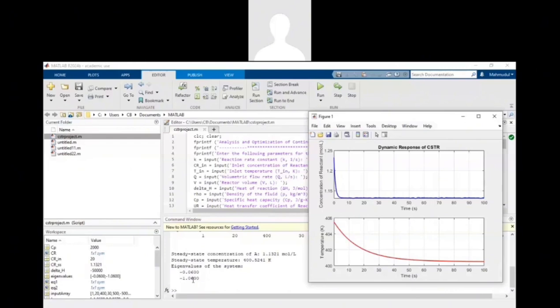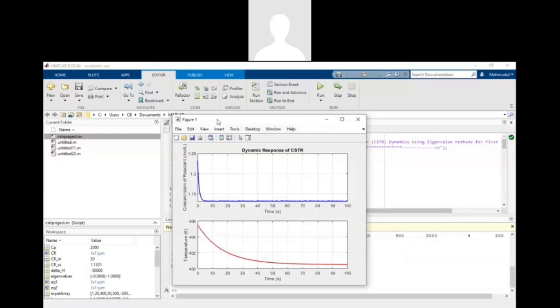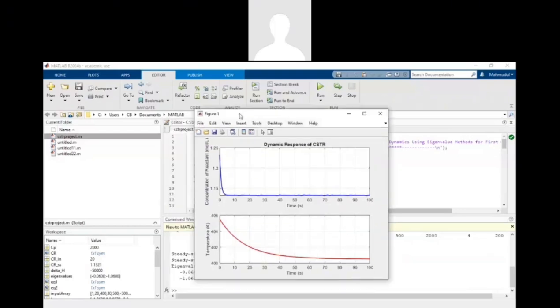This negative value of the eigenvalue is very important, since it indicates that both concentration and temperature under small perturbation over a certain time do not increase unboundedly. Rather, they actually decrease and recede, and the system recedes towards a steady state process. Therefore, based on this simulation, we can conclude that our model allows the CSTR reactor to reach stability and steady state under a certain time.